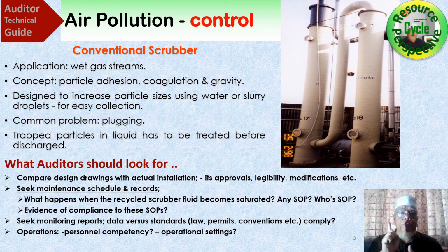Let's talk about the scrubbing agent. The liquid which forms the mist cloud inside the scrubber chamber or column. This liquid scrubbing agent is converted into fine particles to form those clouds of mist by means of the Venturi effect. Well, let's cut the crap of physics and make fluid dynamics fun. In the book, it is called atomization, meaning the liquid is transformed from liquid into mist. Lots of mist, very dense pack of mist, literally.